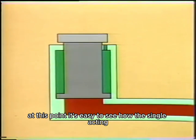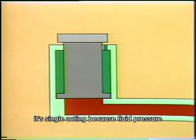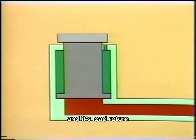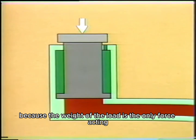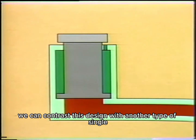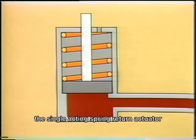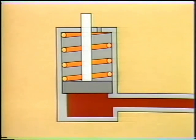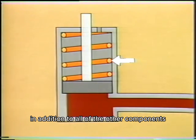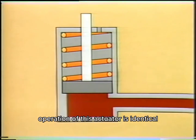At this point, it's easy to see how the single-acting load return actuator gets its name. It's single-acting because fluid pressure acts on only one side of the piston, and it's load return because the weight of the load is the only force acting to return the piston to its original position. We can contrast this design with another type of single-acting hydraulic actuator, the single-acting spring return actuator. This design incorporates a spring in addition to all of the other components common to the load return actuator. Operation of this actuator is identical.